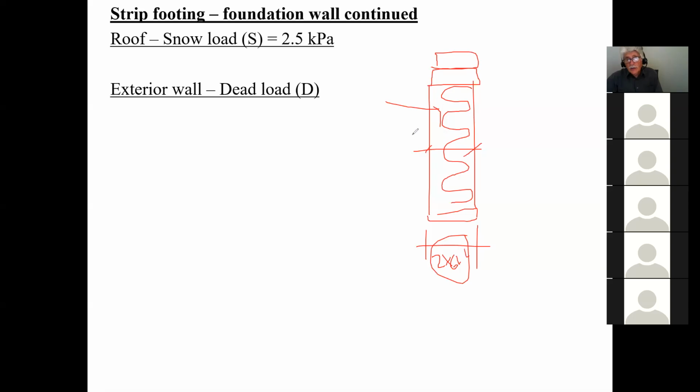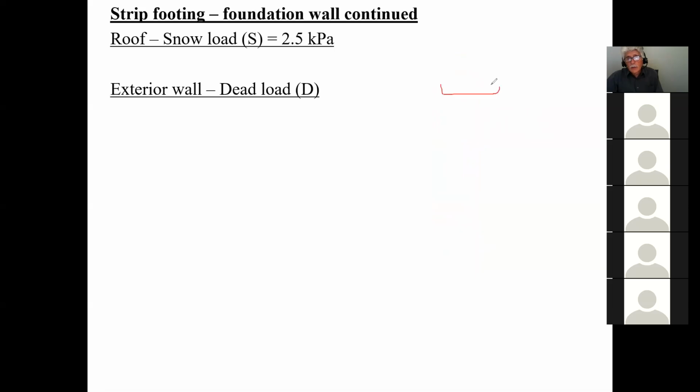As far as the width of the stud here, this is going to be a 2x6, okay? And of course, we're going to have some insulation, and two sill plates up here because it's a bearing wall. We're going to have our stud here, and our stud here. We have our insulation, I should change color, so I have my insulation in here.